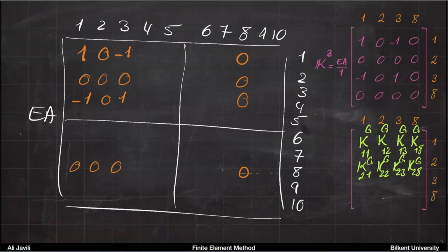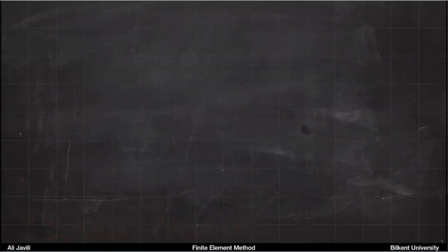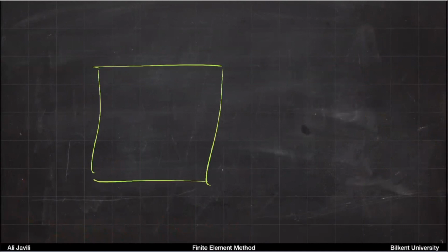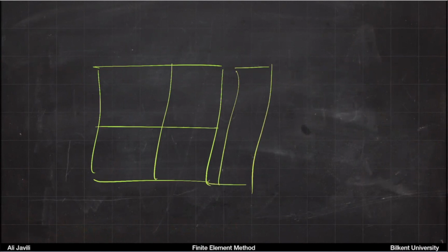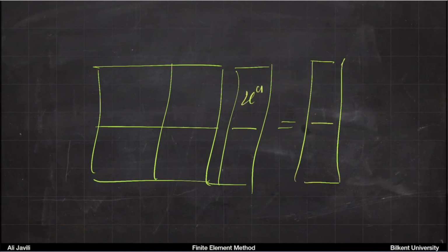Okay, and once you have that matrix, then you have that system that we talked about previously, that reduced system. So you would have a stiffness which has these 4 parts, then you have a displacement that has these 4 parts, and you have a force that has these 4 parts.